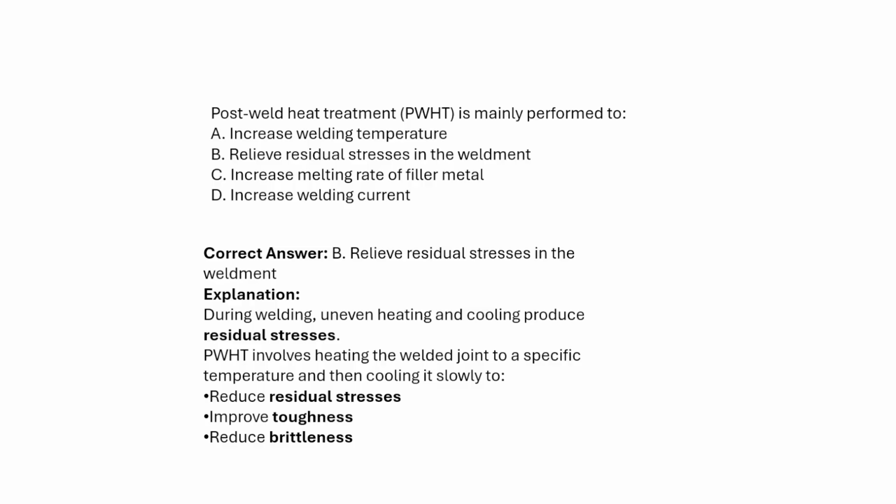Okay, explanation. During welding, uneven heating and cooling produces residual stresses. Post welding heat treatment involves heating the weld joint to a specific temperature, then cooling it slowly to reduce the residual stresses, improve the toughness, and reduce the brittleness.